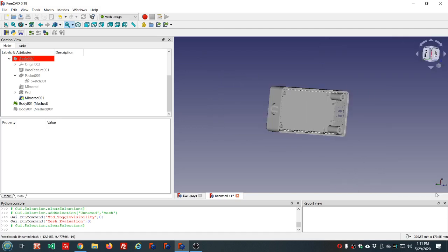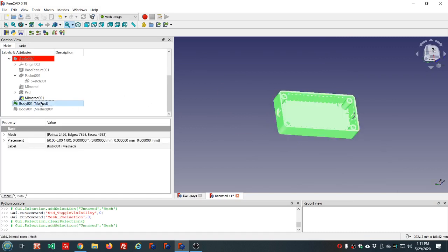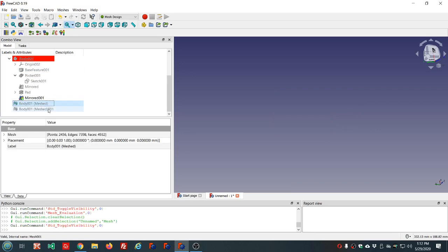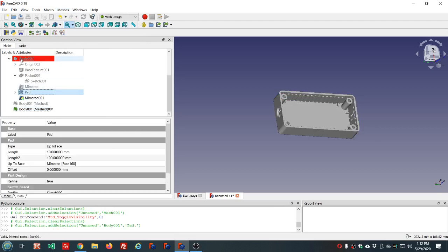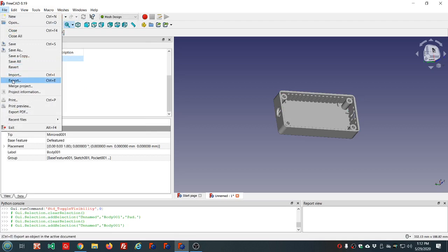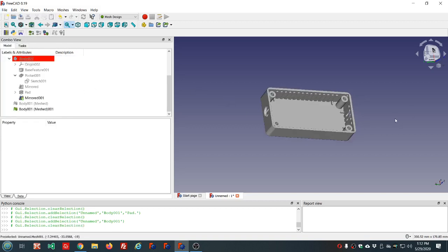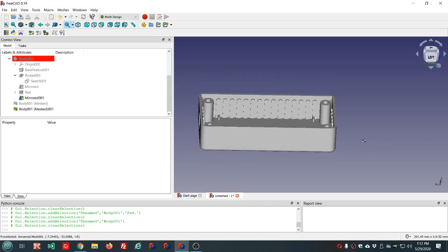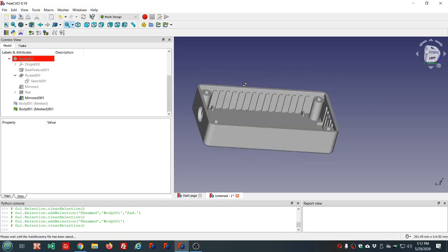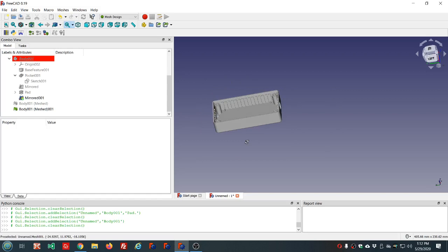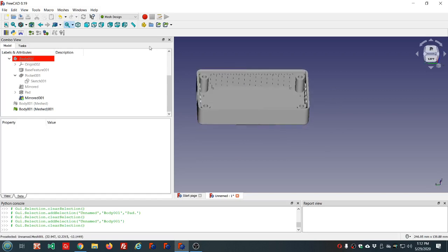So this thing would be now ready to go. I would export. You probably would choose the better looking one. Export mesh from here rather than selecting a body and going here and exporting. If you go here and export, you don't get the options and you don't get to test the STL. You don't get to test the mesh before exporting it. Or you could bring it in afterwards and run that same check on it. That would work too. It's probably using just the standard default.